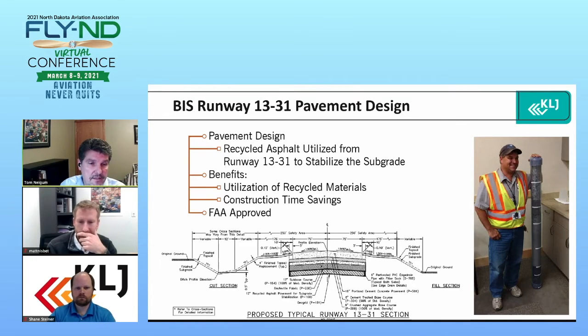We had 8 inches of P209 crushed aggregate base course, 6 inches of cement treated base, and then the icing on the cake was the 16 inches of concrete. And there you can see a photo of Troy Estes, the Bismarck Airport maintenance supervisor, holding a test tube, if you will, of cores from the runway. So that's actually what you're seeing him holding up and smiling alongside is actually the pavement section for the Bismarck